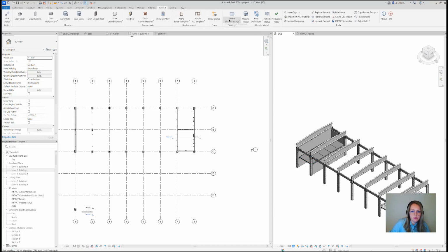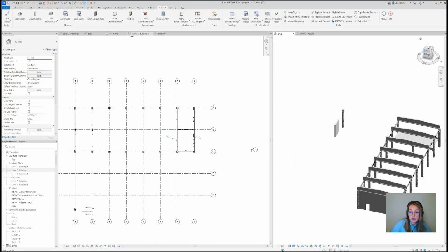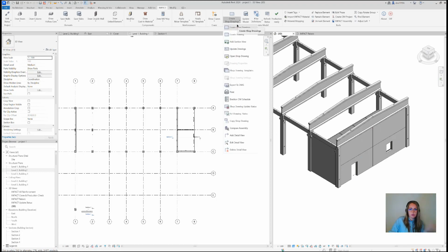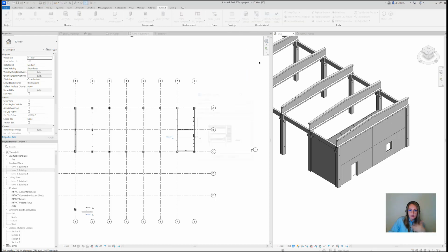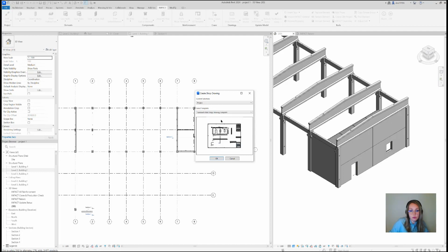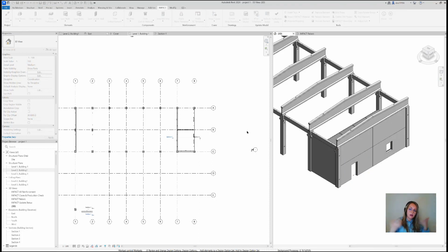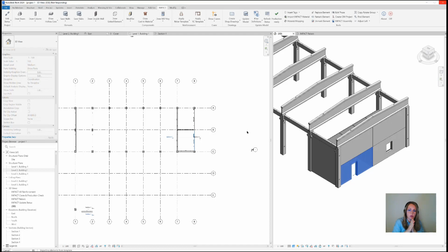Last but not least, I want to demonstrate how you do a shop drawing, and we can do this with one of the sandwich wall elements. So what we're doing is that you say create shop drawing. We have a whole drop-down menu with a shop drawing, and this is done with the help of a shop drawing template. So I'm going to take one of the elements that we've just drawn in Impact. We save it, and I'm making a shop drawing based on a predefined shop drawing template.